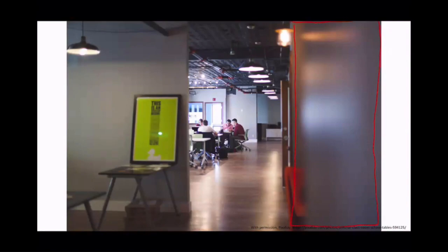But as a non-separated occupancy, if you choose that path, you don't have to separate the two. So the landlord's storage and the big 20% of the floor area storage for the accounting office, if you choose the non-separated path, then you don't have to rate those barriers.